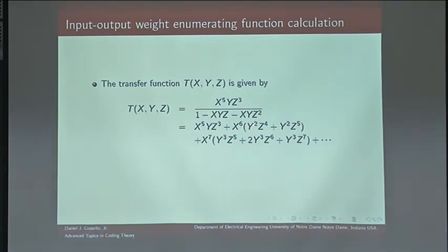And then the 2 weight 6 sequences are both generated by input sequences of weight 2. One is of length 4, one is of length 5, etc. So it gives you more detailed information about the code. And in particular, the X and Y information is useful if you're trying to analyze a turbo code. That's this input-output weight enumerator that we showed briefly.